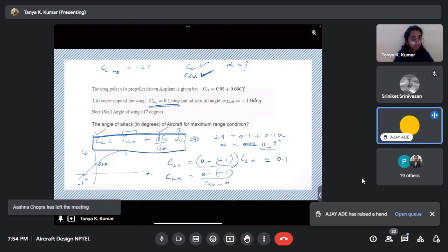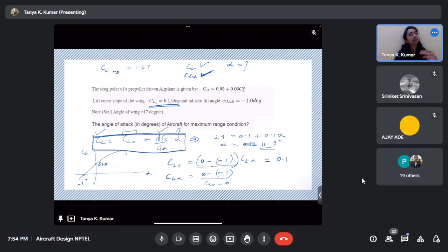Design the winglet. I don't think there are any such parameters. It's just that you smoothen out the flow. If it was a sharp wing tip, the flow intercepts at this point and at that point there is an instability, correct? So you smoothen out the flow, you reduce the magnitude of the flow at the intersection. The basic cross section will be the same. It will still be an airfoil cross section, just of reducing length. So it will be tapering, reducing chord, but with the same airfoil cross section. Maybe narrower. That's all.